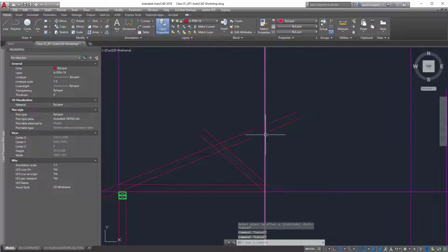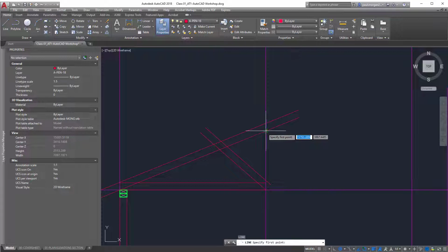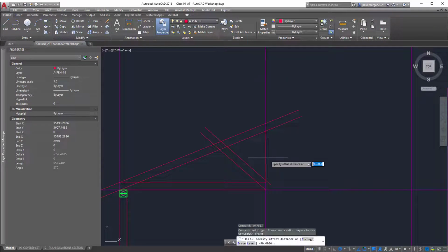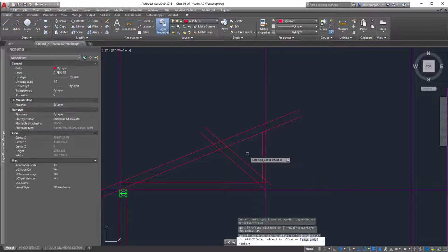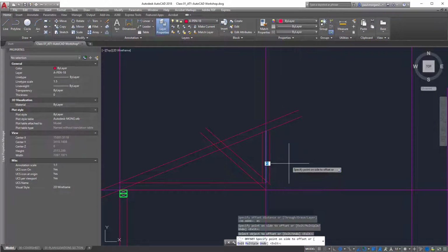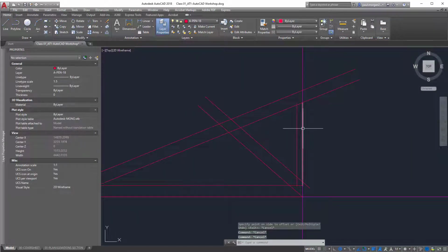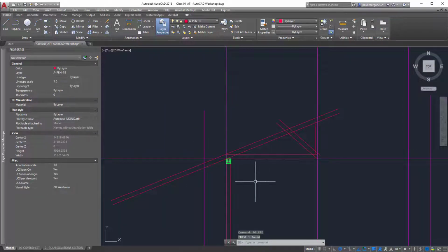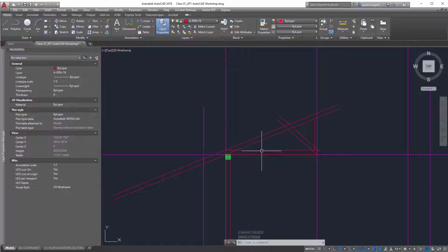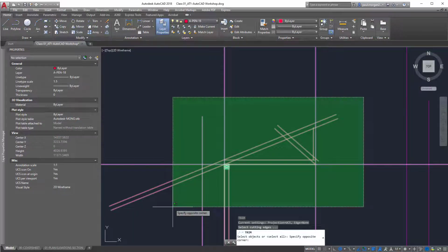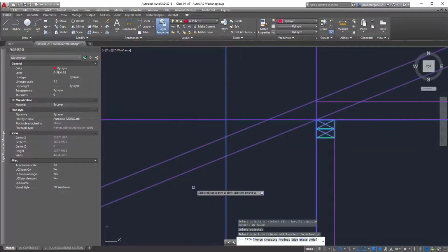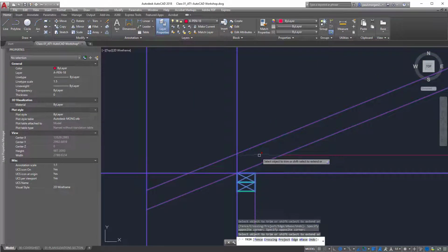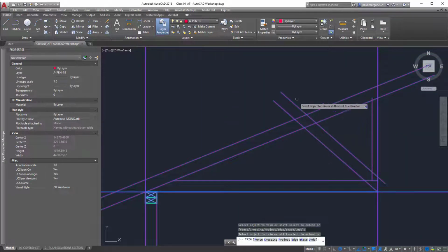And because this is the center point of the building, or the center line of the building, I want to draw a line from here to here for my central webbing, but then I only want to offset that 45 because the other 45 on the other side gives us the 90. And I'll delete that. So that's now complete. We can start trimming back this whole roof truss. So I'll use the trim command. I'm just going to select every element and just start slicing away.